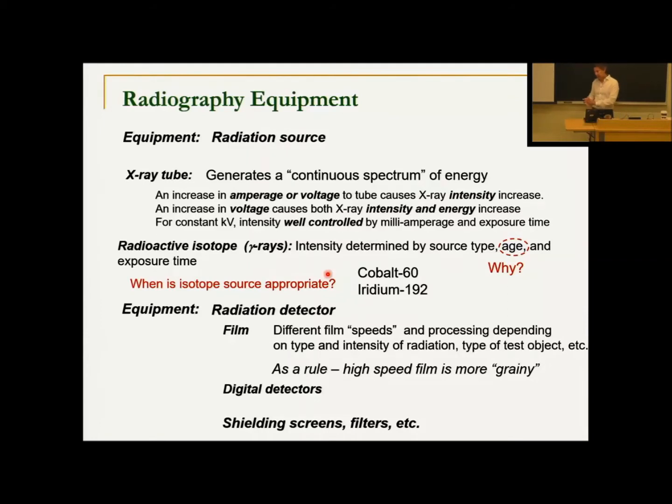Now, to detect the X-rays, we need some way to have some sort of photodetector or film in order to indicate the intensity that comes through with a given exposure time and so on. Now, in previous times we used film, like photographic film. This is the same thing. Film interacts with the photons of light that come through and change color. Well, X-ray films interact with the photons of penetrating radiation and change their color or their darkness, right?